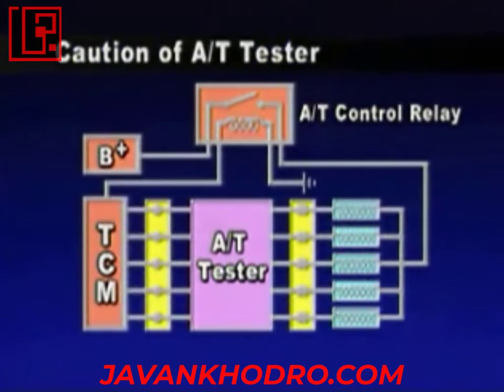While the auto tester is operating, shifting shock happens whenever the gear is shifted because it is not controlled electronically by the TCM. Since the solenoid valve connector is open, the fail code is memorized. Therefore, the fault code should be detected by using the diagnosis equipment.